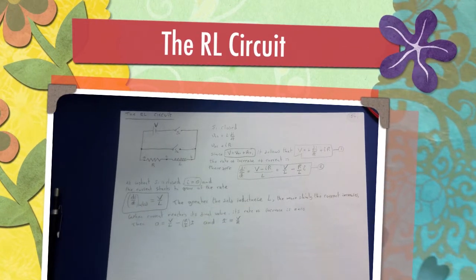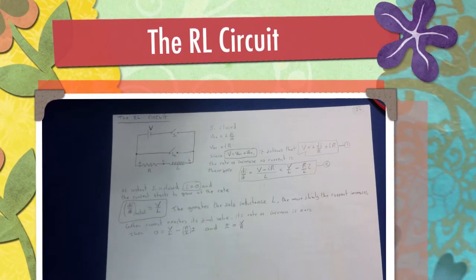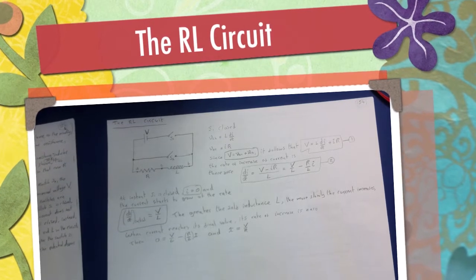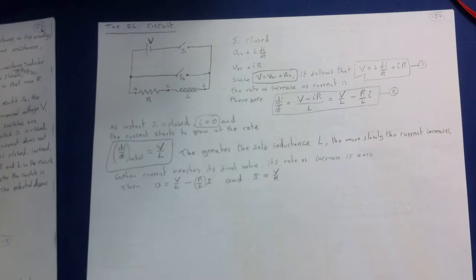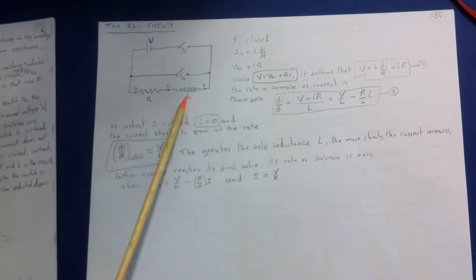In our discussion of inductors thus far, we have neglected the resistance of the windings, but every inductor found in the real world must have some resistance unless its windings are superconducting. So we can represent a real-life inductor as an ideal zero resistance inductor with self-inductance L in series with a resistance R as shown. So here's the resistance R and the inductance L. This diagram can also represent a resistor in series with an inductor. In that case, R is the total resistance.